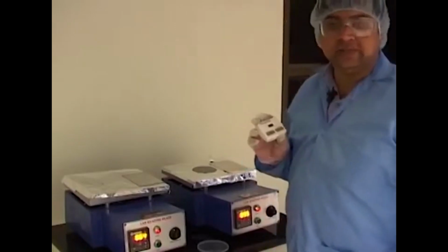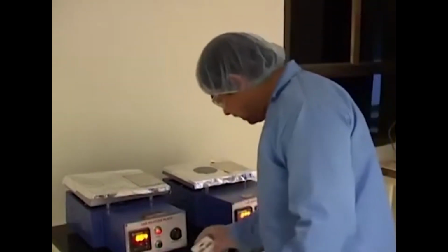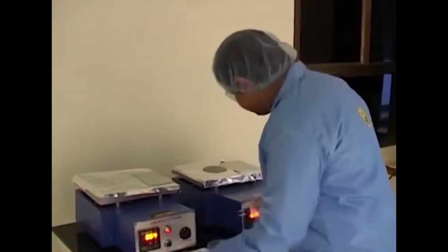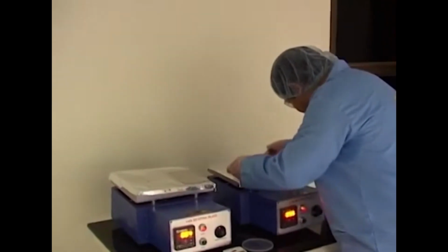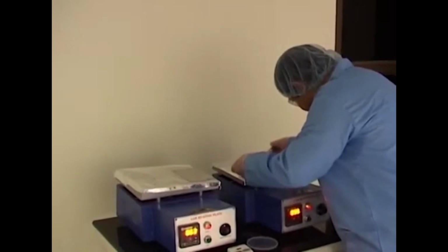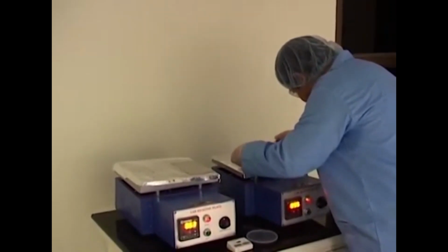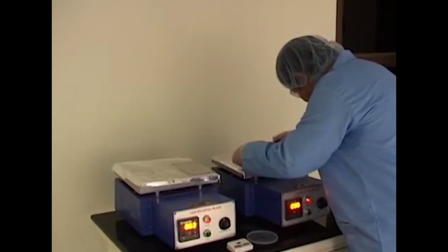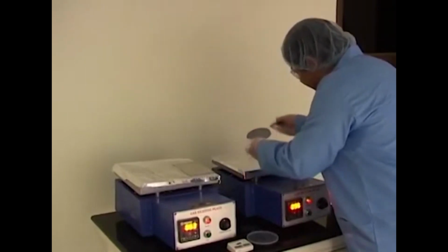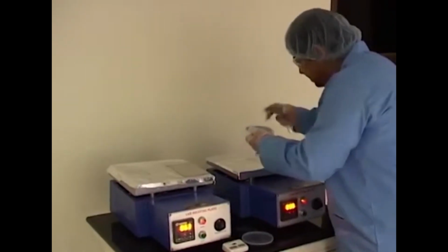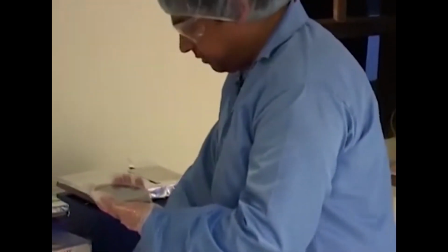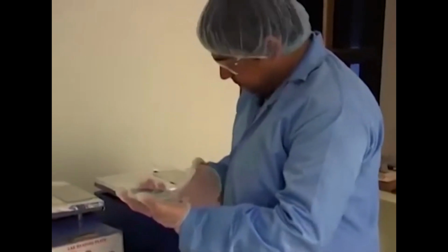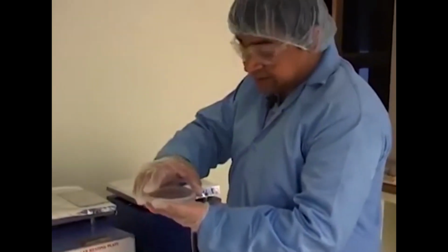So we are nearing the end of the time that it takes, and there is an alarm bell now again. So what we have to do is the same thing. We'll pull back the wafer from the surface here, use just a small area to hold the wafer with the tweezer, and then put it back again on its resting place, where we'll use a little bit of time for equilibrating it back to room temperature. So after this temperature is close to room temperature, we are ready to do lithography on this particular wafer.